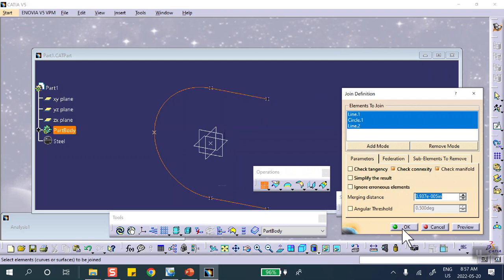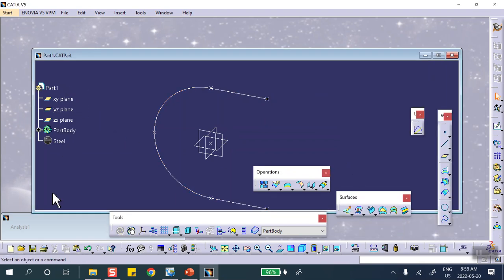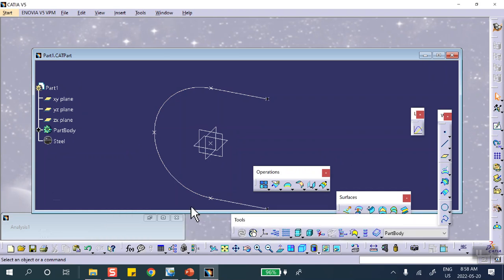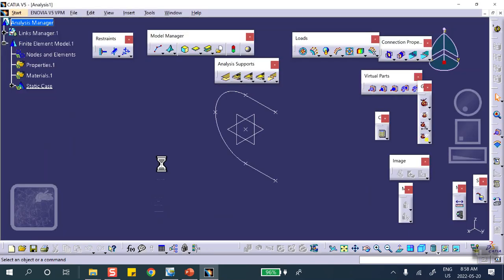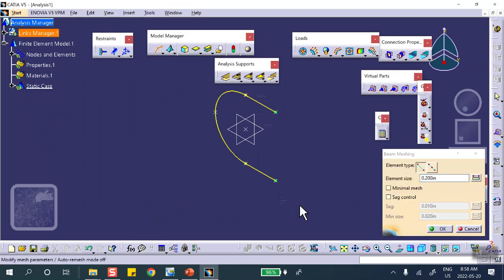Say okay. No problem. Let's go back to our analysis. Now, when I go and mesh, the whole thing is going to be done at the same time, and there won't be any different nodes at the same location anymore. They will move together. Say fine.